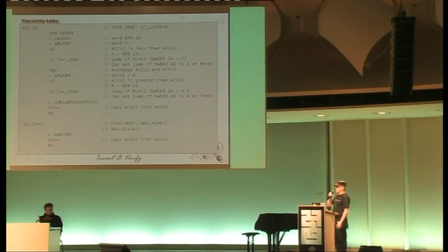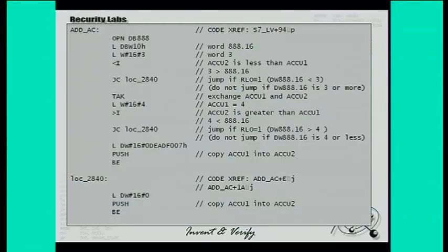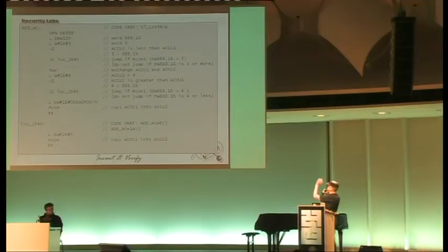Then it's loading a 3, the W#16# just means base 16. And what you see here, you have 2 loads after each other. Now I said you only have 1 accumulator register, and nobody complained. You're not paying attention. So what actually happens is, once you load into the accumulator register, the former contents of the accumulator register are shifted into a secondary one, because otherwise you couldn't compare. Which is what happens next. It compares whether accumulator 2 is less than accumulator 1.